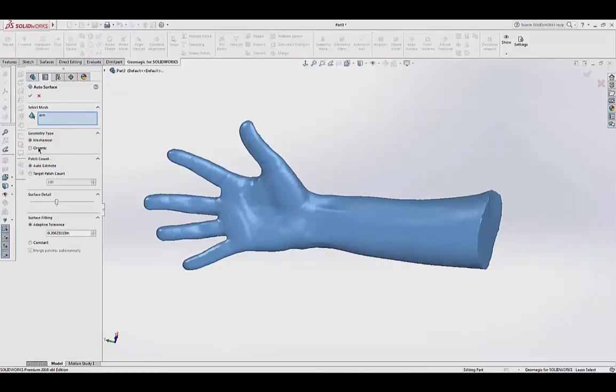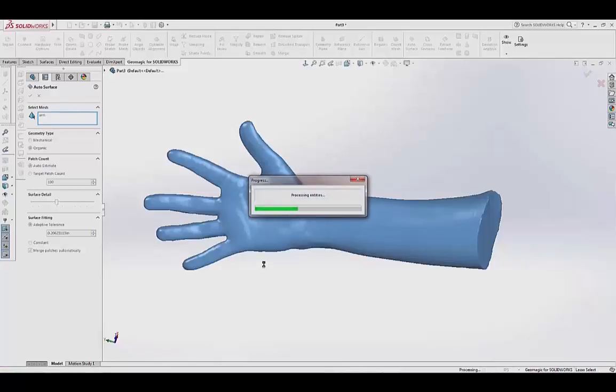So the first thing I'm going to do is harness one of the most powerful tools in here, this auto surface tool. If I have a highly organic shape, that's what this is really powerful for, I feel. I can throw a scan data set in here, tell the software to automatically fit surfaces to it. Now this is a bounded shape, so when our plugin finishes, it's going to create a bounded surface object, which is a solid.